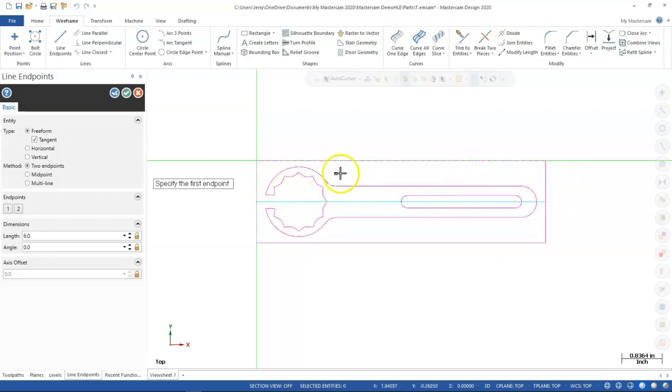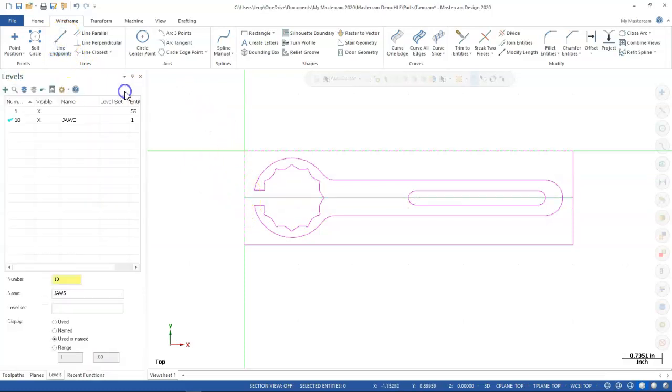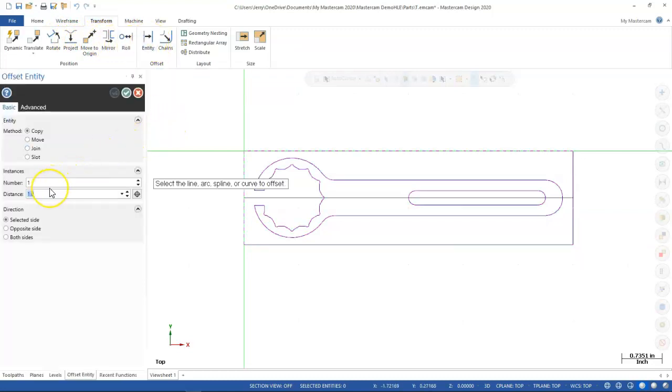And pretty much on the backside, all we're doing is machining off all of that sacrificial material. So that being the case, then let's go ahead with a line. Actually, let's just do an offset. So on the transform, we'll come back over to an entity offset. And like I said, an 1/8 of an inch should be plenty. We'll offset it to the inside, accept and do it again. And accept and do it again. All right.